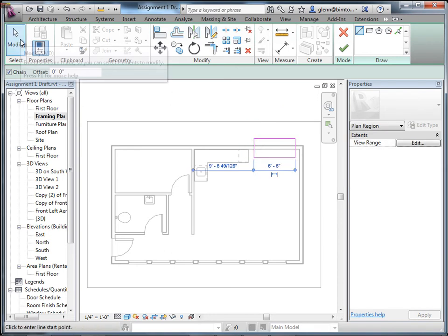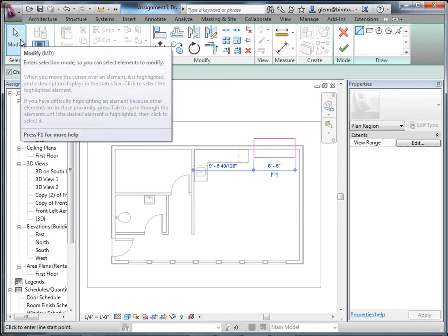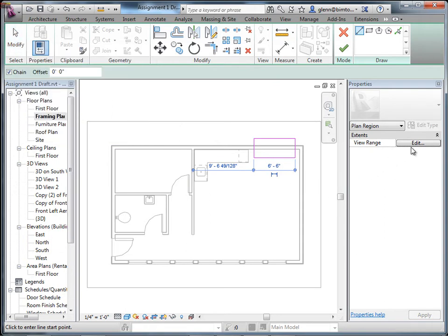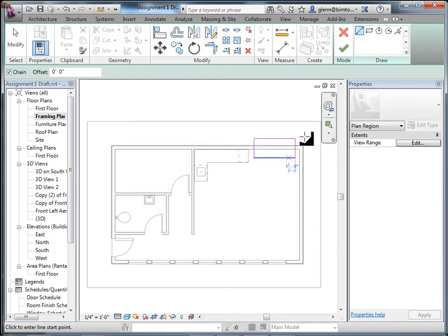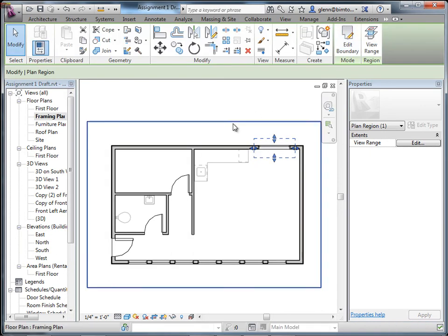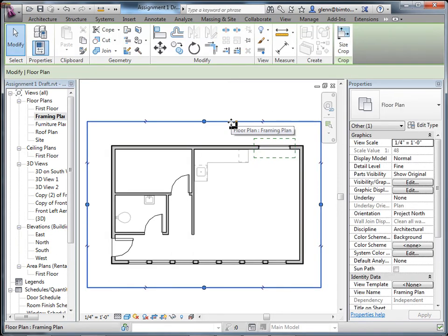Since we're doing areas, all the pink line rules apply. So it can't intersect, can't overlap, has to join. We can say in that little area right there, what I would like to do is change the view range. So I'll make it 6 feet just there. And when I finish that, you get a very funny little thing. It's a little window that pokes through and gives you a different view range just in that spot.